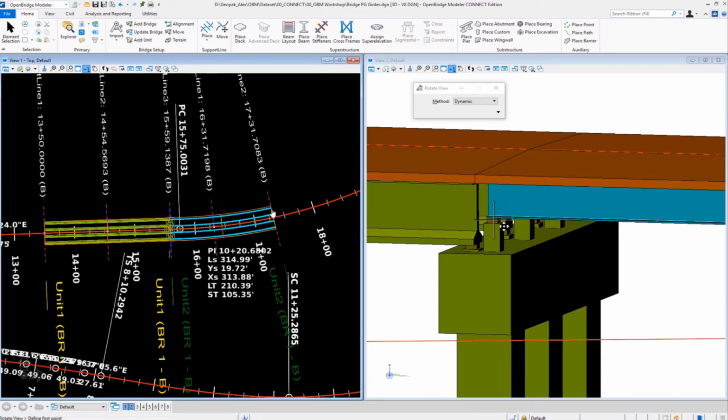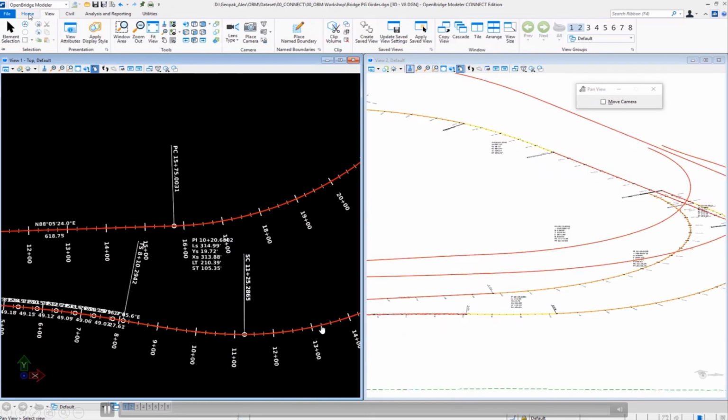Right? It's up to the user, the engineer, to transfer the dead loads. When analyzing the concrete one, it may need to bring the loads that are coming from the steel part and apply them to the proper bearing on the pile cap, and vice versa. So that is left to the engineer's criteria to apply those dead loads, right?